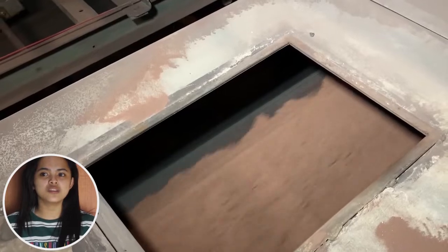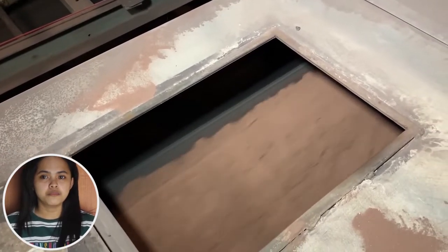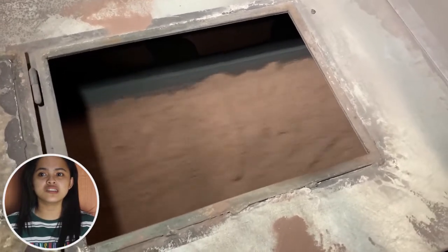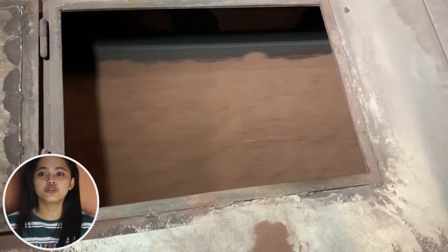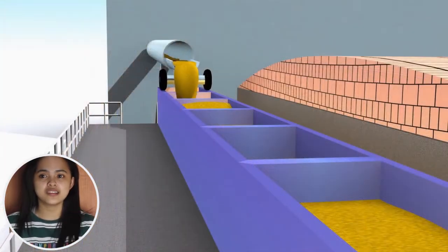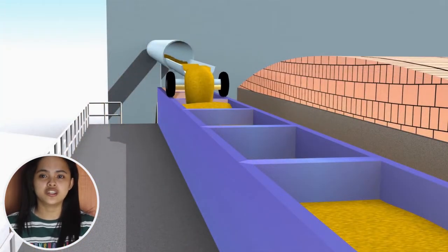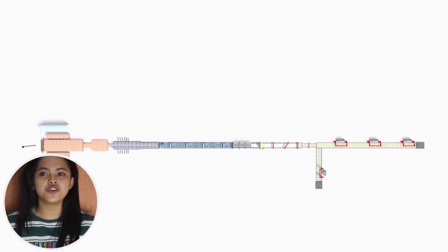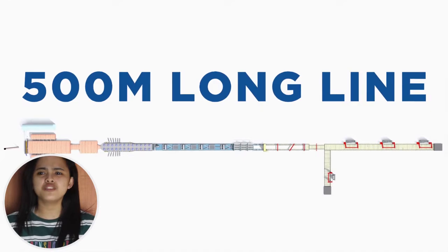Effective batch mixing is key to the melting process. Best glass quality can only be achieved when the batch has the necessary homogeneity. About 4 to 5 tons of batch are conveyed around every 5 minutes to be distributed in the batch charger. During the process, a flat glass ribbon of uniform thickness is formed on a 5-meter long line.